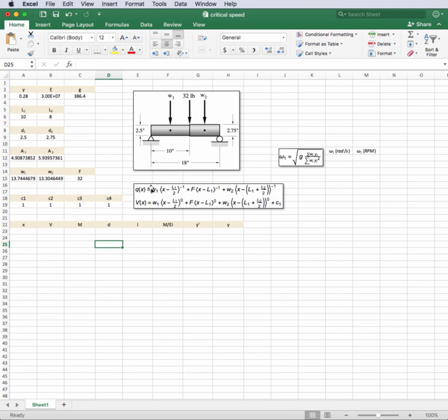Doing this by hand, I just have the three forces right there in my distributed load. So I've got W1 acting at L1 over 2, that's 5 inches in, right? There's the force acting at 10 inches in, and then the W2 there acting at 14 inches in, it looks like. Okay, I'm doing this integral by hand, just writing this down on a piece of paper or something. So here's the shear force. If you remember how to integrate these things, the negative ones all bump up to zeros. That's the only difference, and then we're adding an unknown constant C1.